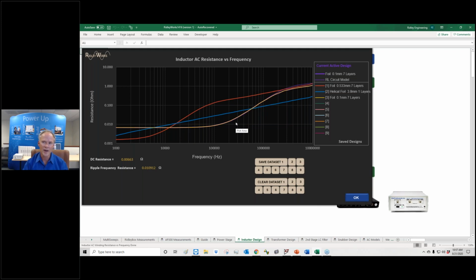And if it's a pure AC winding, so if it were a forward, a full bridge converter, or a half bridge converter, LLC or non-LLC, you're actually going to be better off sometimes with multiple layers of foil, depending on your voltage levels. Okay, so there's never one answer. There's never one inductor that solves everything.